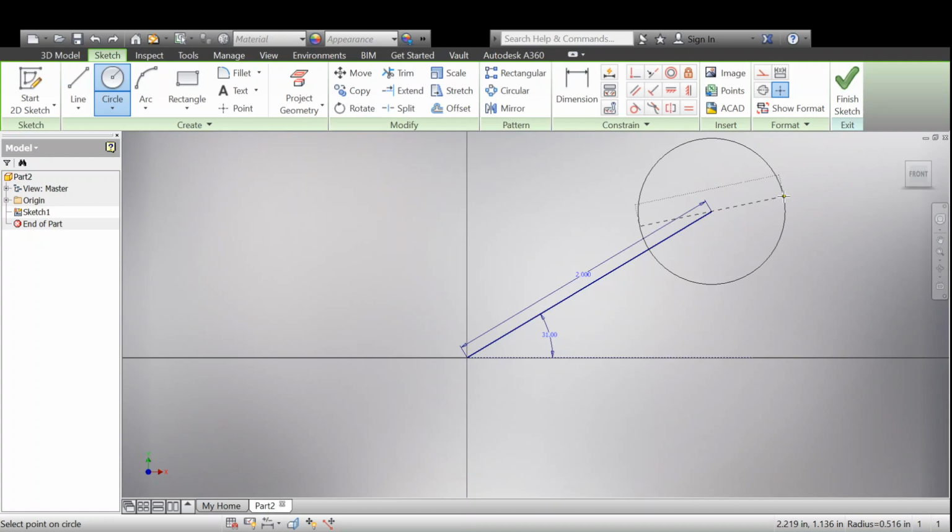We can either move outward and click and make it an arbitrary diameter, or what can we do, like we did last time? We can type in the direct dimension right into here. So I want to make this circle 1.5 inches in diameter. And right now, I know it's measuring the diameter because I literally see this, which is the diameter that's showing. There are other ways to use a radius instead of a diameter, and we'll see that when we get to arc features, arcs. So let's type in 1.5, please. Hit enter.